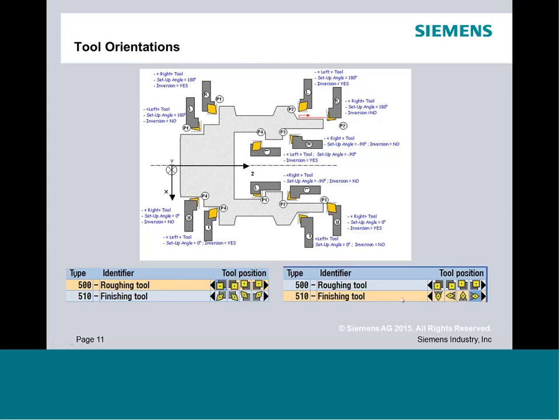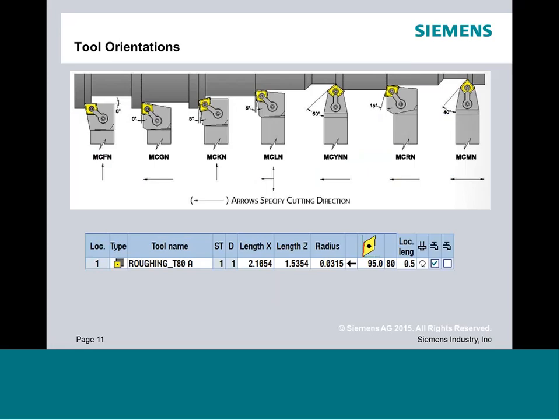Handed tools, we can see on the right lower corner, neutral tools. So that's the first and most basic. We've got to tell it roughly where the tool is sitting. From there, you're now going to get into how the insert physically sits in the holder.